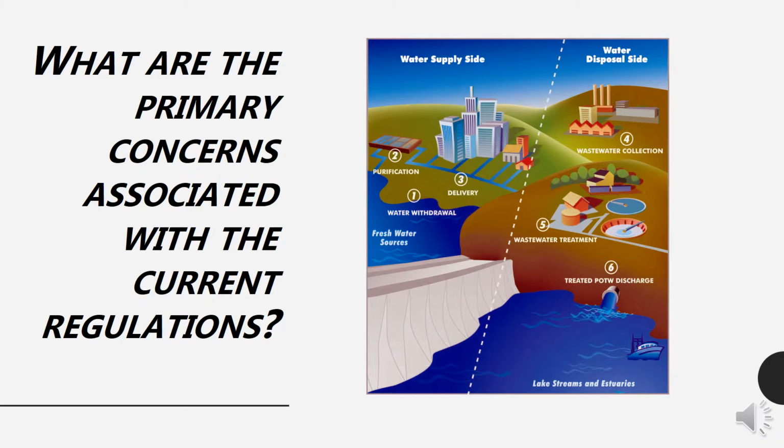Thresholds for DBP levels in finished drinking water were chosen to reduce public health risks based on available toxicological and epidemiological data. The classes and individual species of DBPs were selected because trihalomethanes and haloacetic acids make up the majority of DBPs in finished drinking water following disinfection by chlorination. Further, the trihalomethanes and HAAs were thought to be surrogates for the hundreds of unregulated and unmeasured DBP species potentially present in finished drinking water and indicators of the toxicity and human health risks associated with water use.